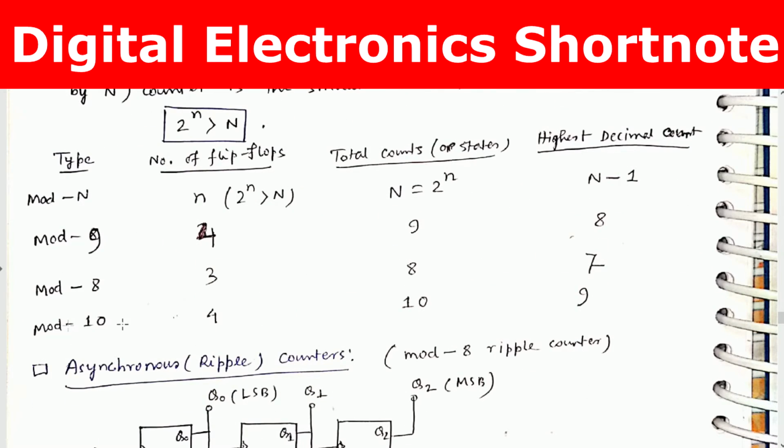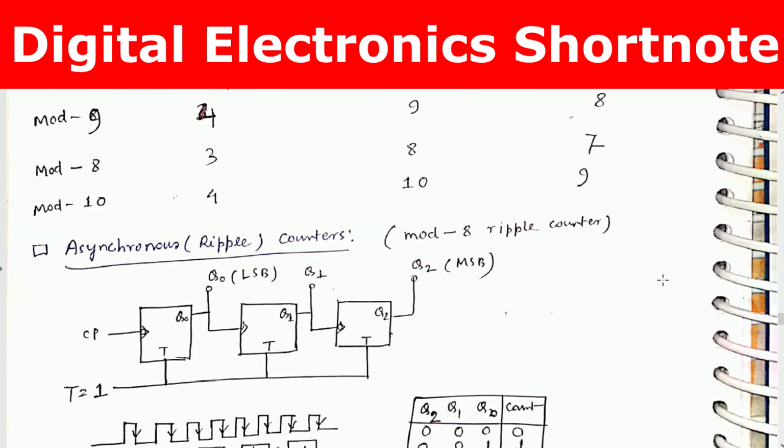This is the type, mod N: mod 9, mod 8, mod 10. So the number of flip-flops n is such that 2 to the power n must be greater than this N. If you take 3 flip-flops, then 2 cubed means 8, which is less than 9, so we have to use 4 flip-flops. Similarly for mod 8, 2 to the power 2 means 4, which is less than 8, so you have to use 2 to the power 3, which is 8. The highest decimal count is N minus 1: for mod 9 it is 8, for mod 8 it is 7, for mod 10 it is 9.